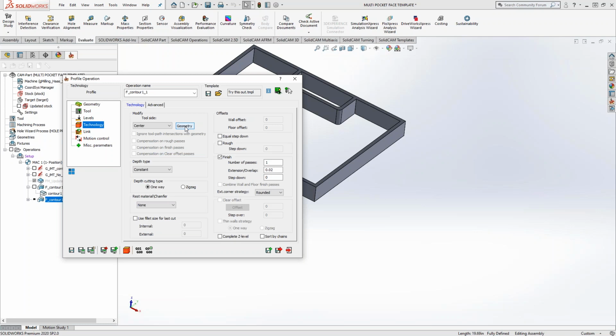Because always remember, there really is no need to add sketches inside SolidCAM, even though you have a great ability to do so because of our integration with SolidWorks. Sometimes there are modifications like you see here to modify the current geometry to get what you're looking for. And in that case, that's why you're not really going to be saving it, because it's a modification for the particular case that you're in. So it doesn't save it. So pretty much takeaway is anything related to geometry is not saved by a template. Everything else is.